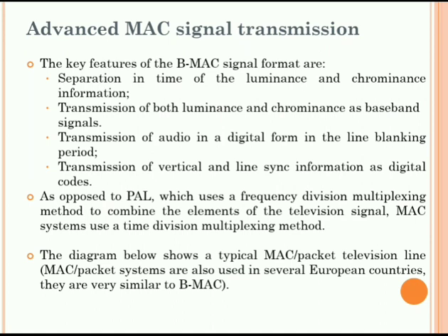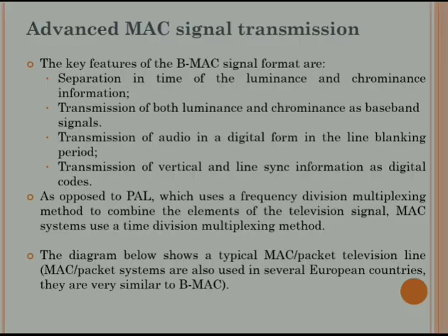The terrestrial TV broadcasters were never able to take full advantage of MAC image quality due to the multiple interactions between their composite and component signal paths. The direct-to-home TVRO broadcasters were able to take advantage of MAC's improved image quality because their studios and routing facilities were far less complex. Thus, the success of NICAM audio for terrestrial television can be traced to the success of MAC technology. The MAC audio subsystem is nearly identical to the design and functions of the NICAM system.